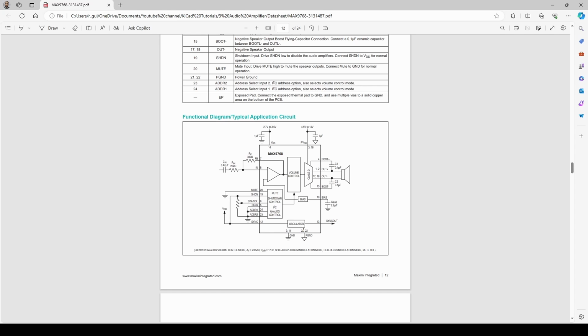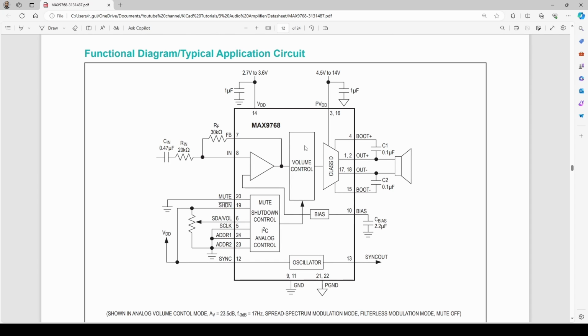Obviously the design is quite simple, but some of the things that we need on this are regulators for the power supplies. So you can see we've got two power supplies on this component. We have a high power supply here, and then we have the digital power supply for the low level logic in here. The typical range for that is 2.7 volts to 3.6 volts. I don't expect there'll be much current going through this path, but we can have a look at how much power will be required for this node over here in the datasheet.